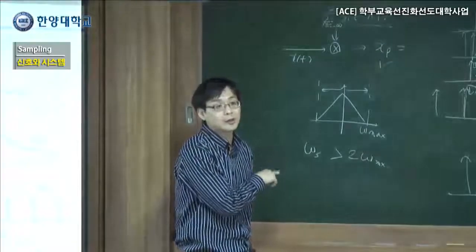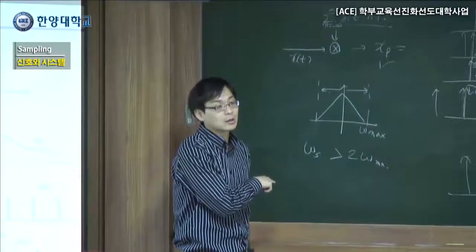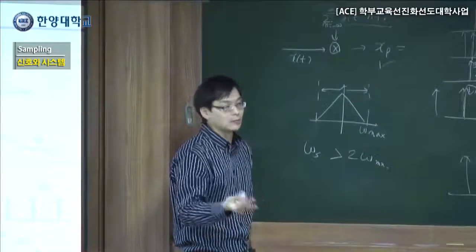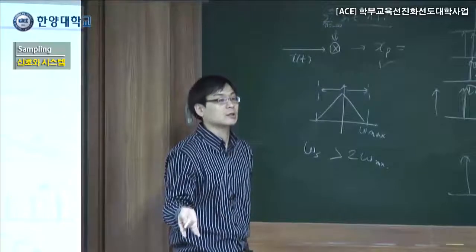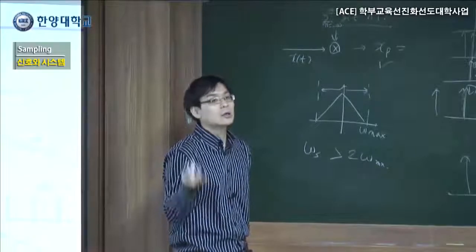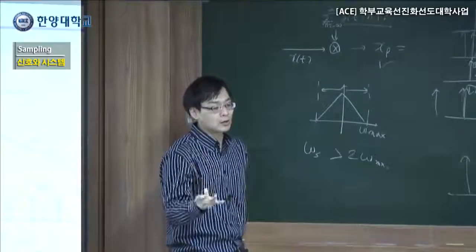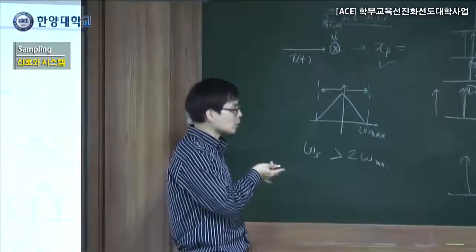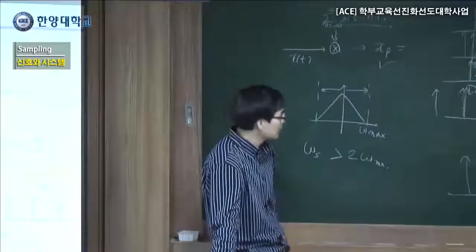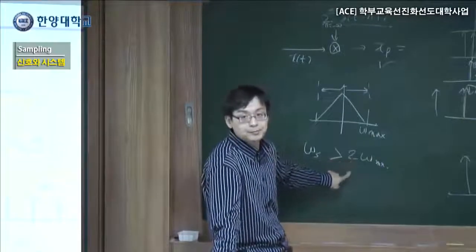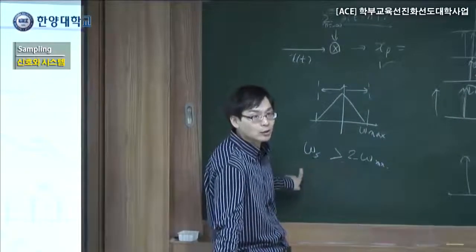I think you already heard about that. This is Nyquist's theorem. You may hear that, okay, the signal has a frequency omega, and the sampling frequency should be at least 2 times larger than that. That's a basic rule like that. There are many ways we can think about this; this is more of an engineering way we can understand, just draw the picture and then see that there's spacing like that. There's a reason there's 2 over here, and there's a reason that it should be larger.